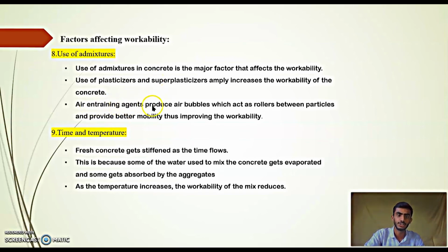Air entraining agents produce air bubbles which act as rollers between the particles and provide them mobility, thus improving the workability. Next is time and temperature. Fresh concrete gets stiffened as time flows. As we know, the concrete gets harder when time increases and the water in the concrete decreases. Therefore, we have to increase the workability. The time should be properly managed.